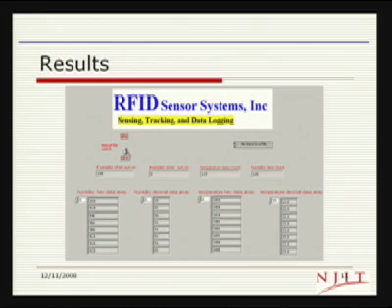We have some results because in the last quarter, our parent company and ourselves designed the prototype for the temperature and humidity tag. As you can see in this picture, there is some raw data of humidity and temperature. On the left, you will see the hexadecimal numbers, which are stored in the EEPROM memory by the microcontroller and are provided by the sensor. And on the right, you will see the conversion to decimal figures, like percentage for humidity and degrees centigrade for temperature.